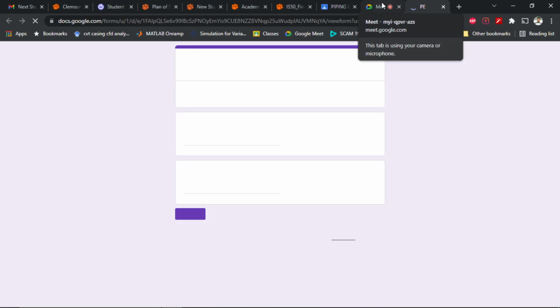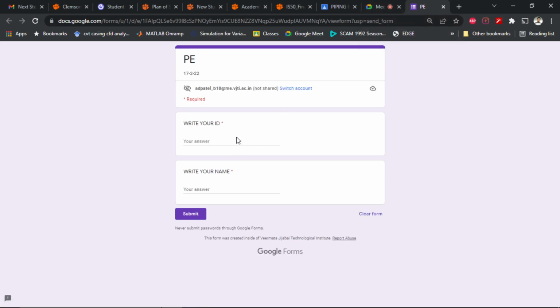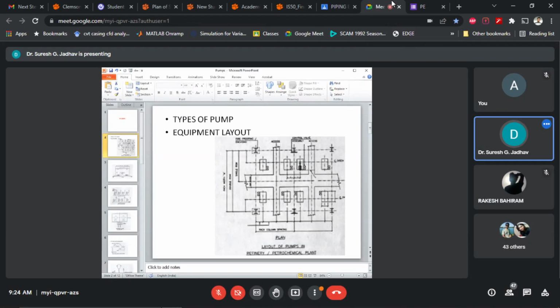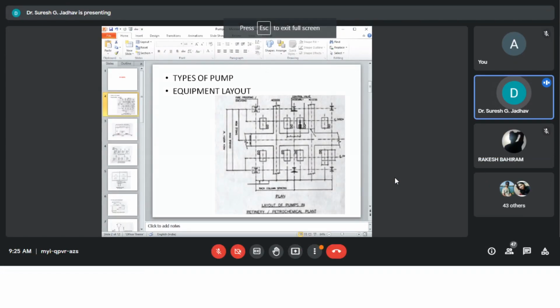The discharge of one impeller is the suction of the next one, and the head developed in all the stages is added. Based on the suction and discharge arrangement, the types of pumps available are end suction top discharge, top suction top discharge, and side suction side discharge.